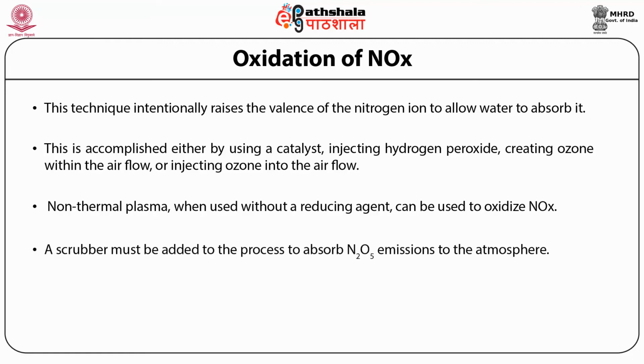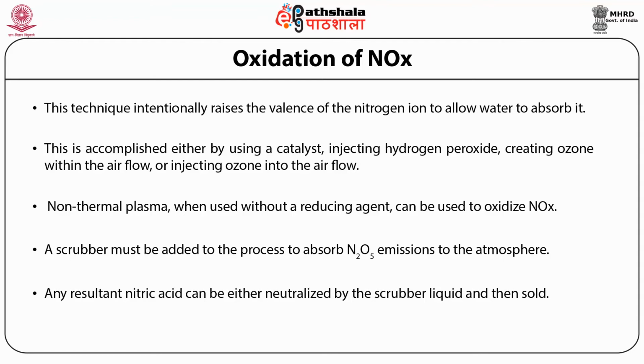A scrubber must be added to the process to absorb dinitrogen pentoxide emissions to the atmosphere. Any resultant nitric acid can be either neutralized by the scrubber liquid and then solidified.